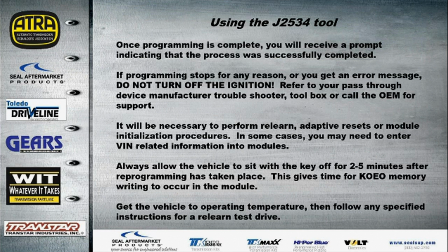Sometimes you might even have to enter VIN-related information. Now, after programming has taken place, you always want to allow the vehicle to sit with the key off for about 2 to 5 minutes. And what this allows for is for the programming to be written into the EEPROM. It's the electronically erasable programmable read-only memory.